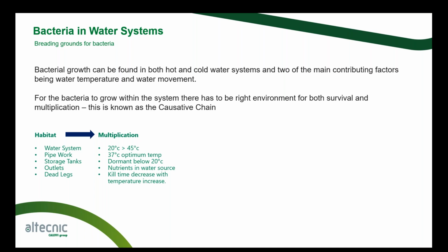Now, the kill time will decrease with temperature increase, and what we mean by that is the hotter the water becomes above a certain temperature, we're going to start to kill off that bacterial growth, and that's something that we will focus and look on a little bit later in the presentation. But the hotter the water becomes, the quicker the kill time of that bacteria becomes.